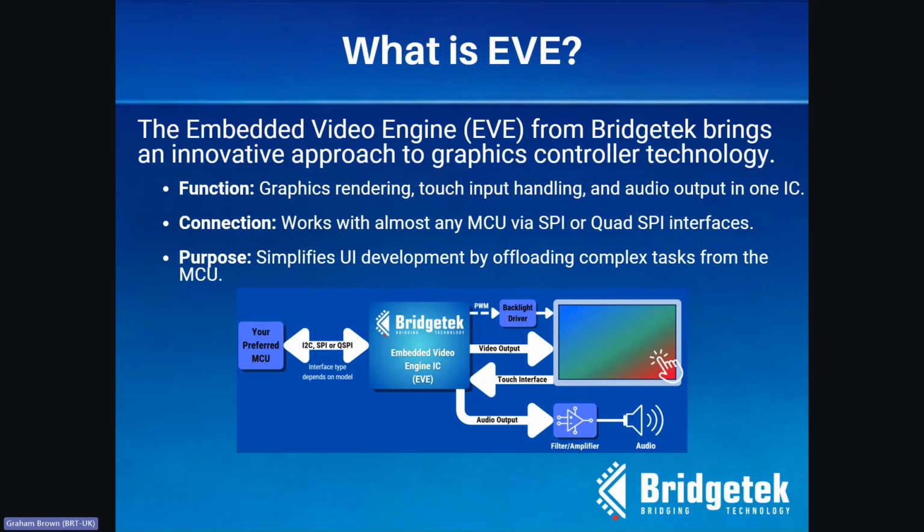The EVE IC also incorporates a PWM control for the LCD backlight drivers, as well as a touch interface, which can support, depending on the EVE model, capacitive or resistive touch engines. It also includes an audio output, which you can connect to an amplifier and speaker and play back audio sounds via inbuilt or custom audio files with EVE.